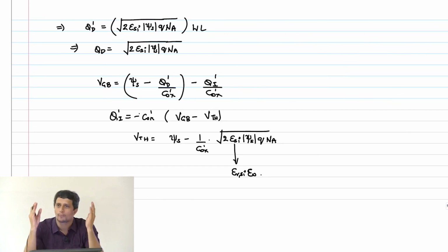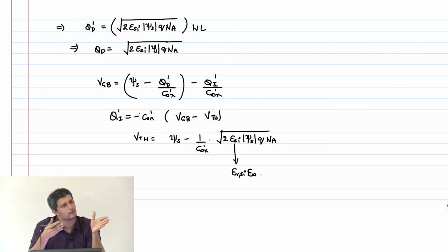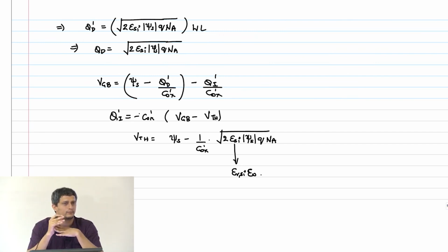So even if you apply a large potential, it is only VGS minus the threshold voltage that is actually available to create more inversion charge and thereby increase the current. Below the threshold voltage, the inversion charge is negligible and you can't do any useful thing with that.